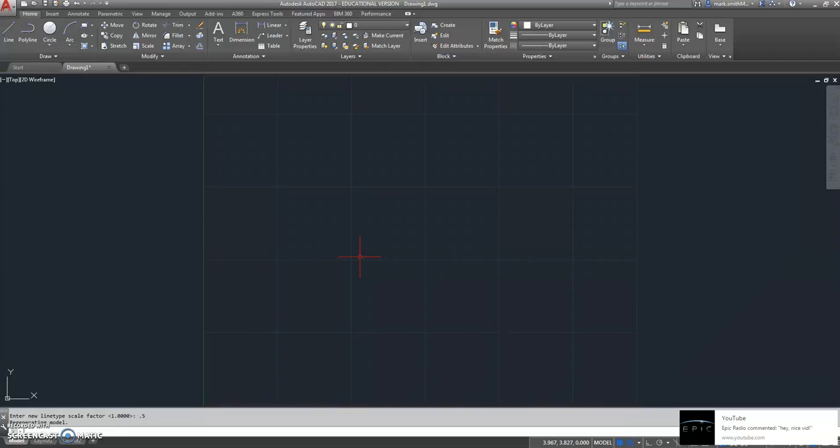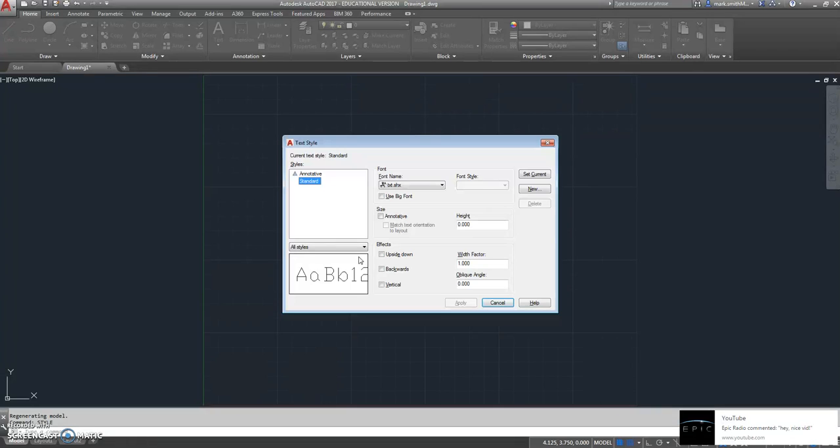And then it says text style. Now, if you've created your text styles already, that's great, but I'm going to set them up one more time. So I'm going to go Style, using Standard. I'm going to go New. With my caps lock on, I'm going to go Mech Text. Click OK. Mech Text is Arial, so I'll go select my Arial. And there it is.